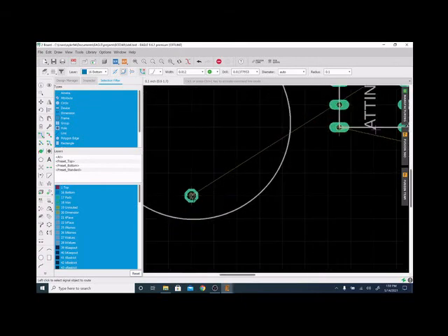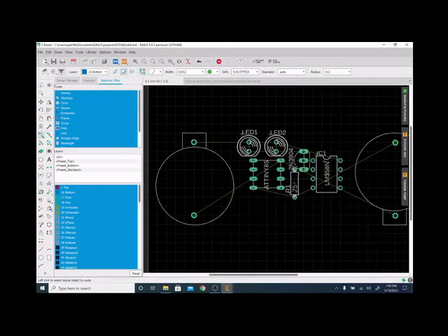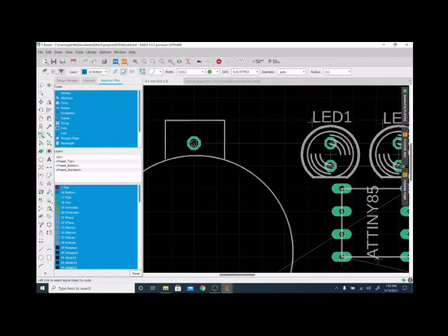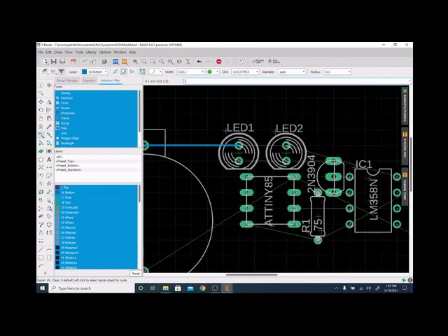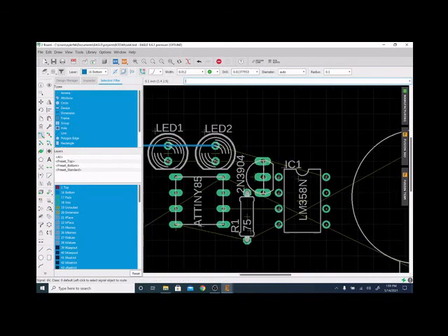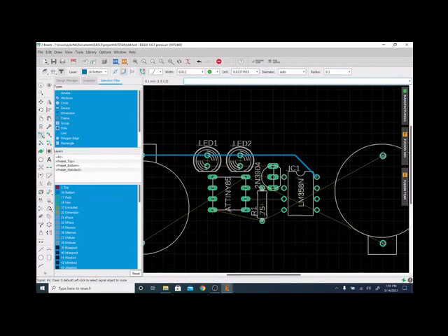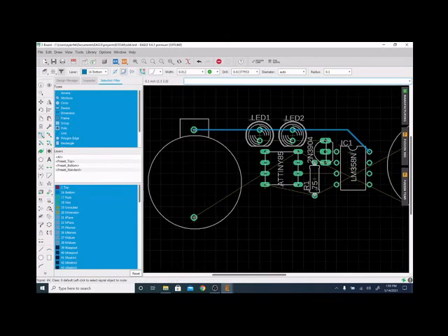And the last thing I need to do is start clicking and going over these wires. So you can tell right here, this is a 6-volt line. If I click on that, it's saying, oh, hey, he wants to start laying this out. So I'm going to put one there. And it'll give you a little ding once it connects. That's nice. One there. And this guy goes there. And I think that's it for the 6-volt line.